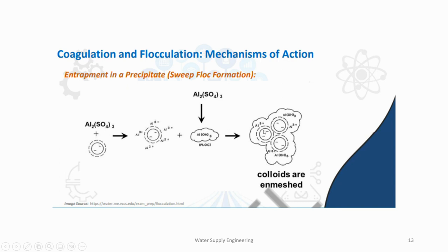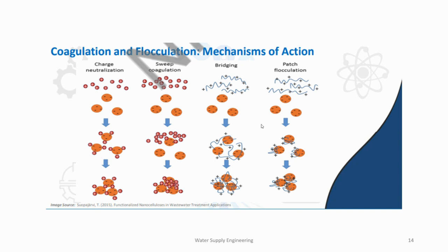So without destabilizing itself, these colloidal particles will be swept out. So thus the mechanisms of action are charge neutralization, sweep coagulation, bridging, and patch flocculation.